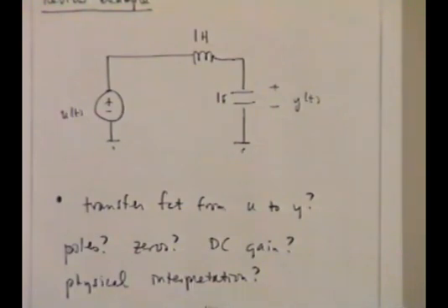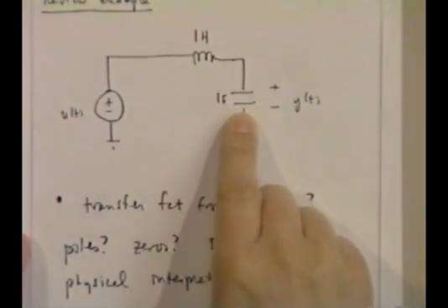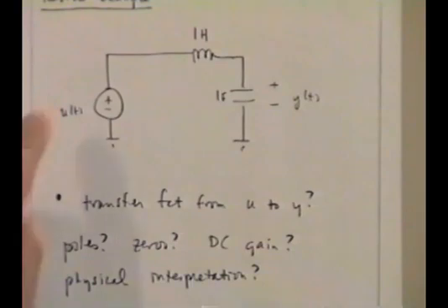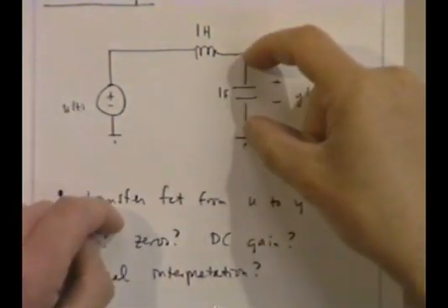No, it's the opposite of a short circuit. Yeah, it's the opposite. It resists. I mean, an inductor resists changes. So when you put high frequency voltage across it, very little current flows. A capacitor, on the other hand, is moving towards a short circuit. So whatever this thing does at very high frequencies, this ought to be low.